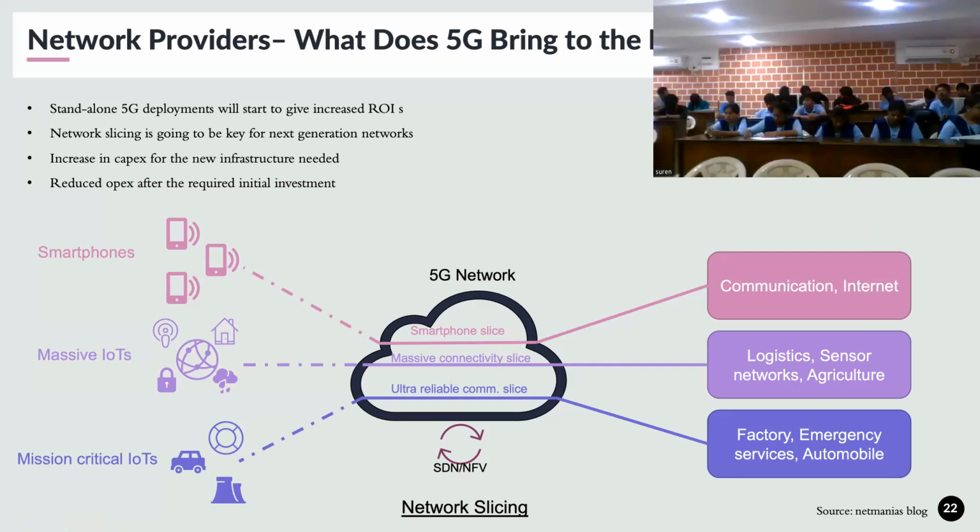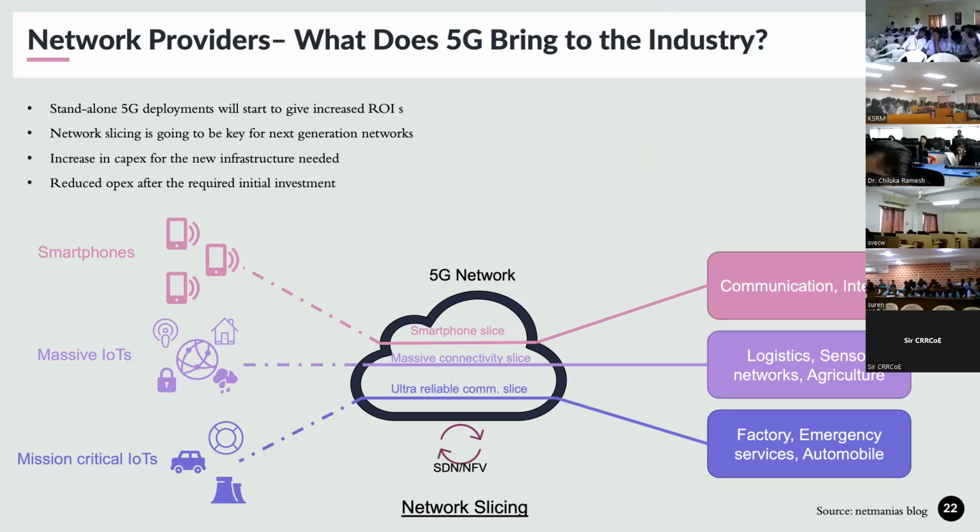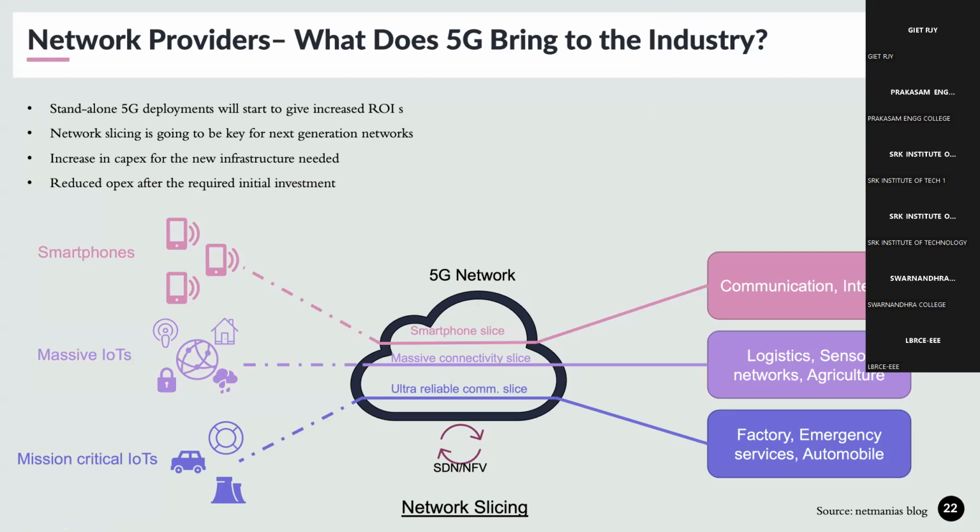You can implement a full adder or half adder using a bunch of logic gates, and you can create a logic gate every time. Or you can create a combination of logic gates just to perform multiplication and keep that hardware in a processor. Every time you just feed inputs and it will give you output. So you don't need to dynamically link all the logic gates on the fly to get to the answer. You already have a predefined multiplier or adder defined in the processor.